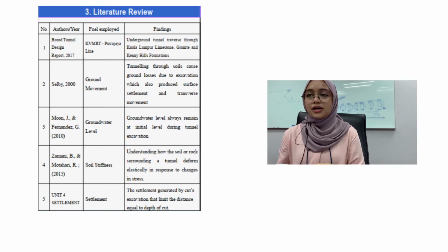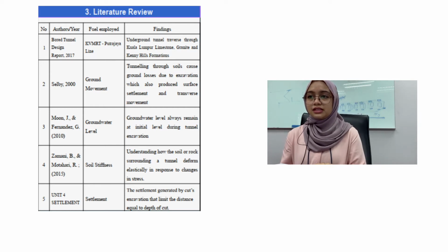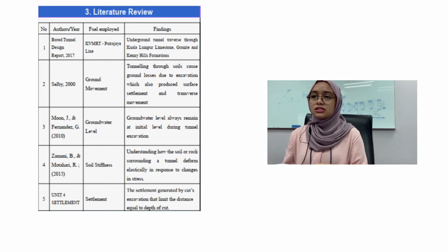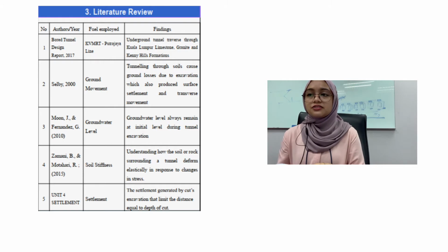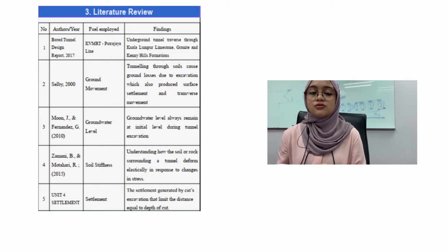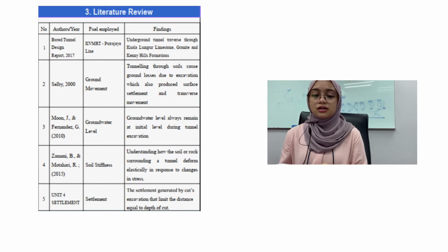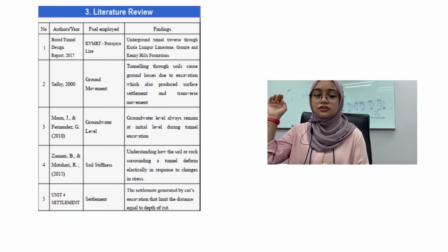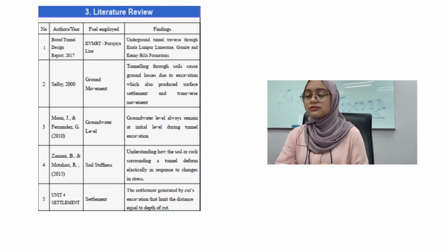Next, by Selby 2000, in terms of ground movement, tunneling through soil causes ground loss due to excavation, which also produces surface settlement and transverse movement. It is important to estimate the effect on the structure when the tunnel is driven below the existing structure.